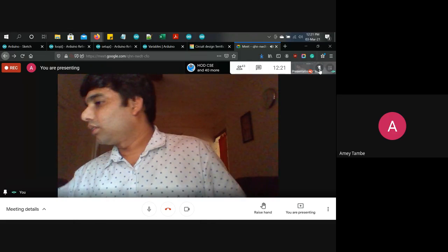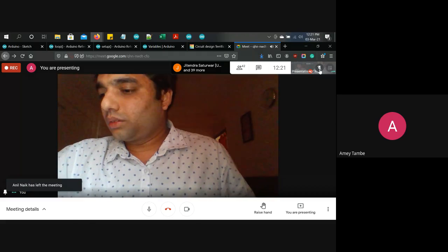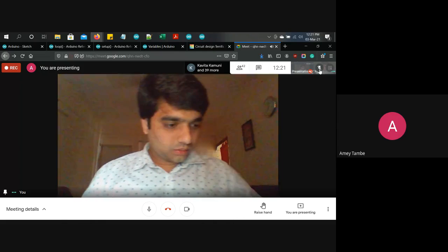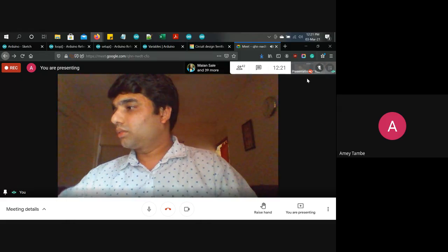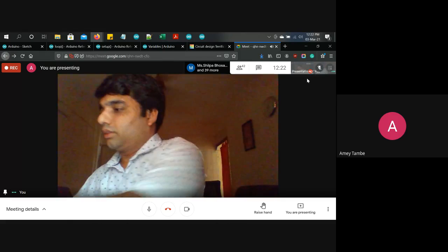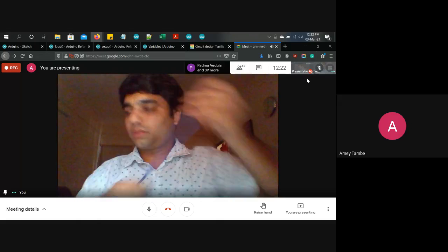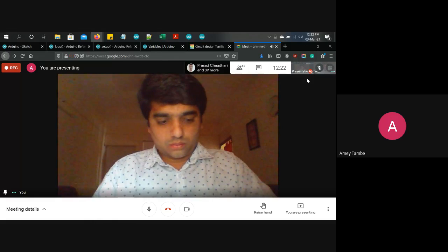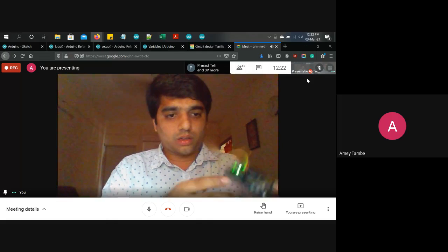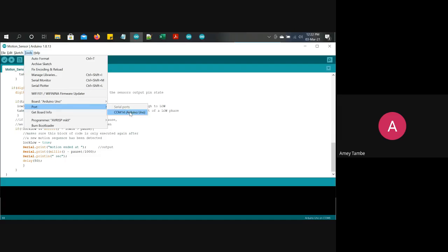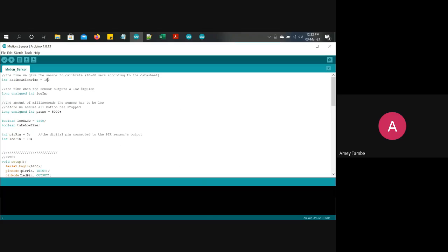Where is my cable? Here it is. I'm just programming it. The same code that we just added to the simulator. It has LED calibration time of 10 seconds, and PIR pin to 3. I'll just upload it.